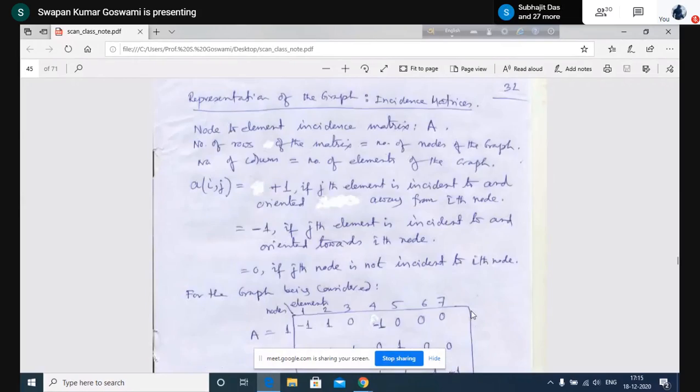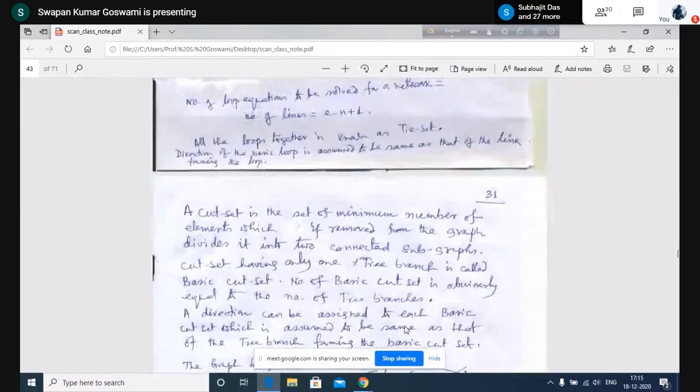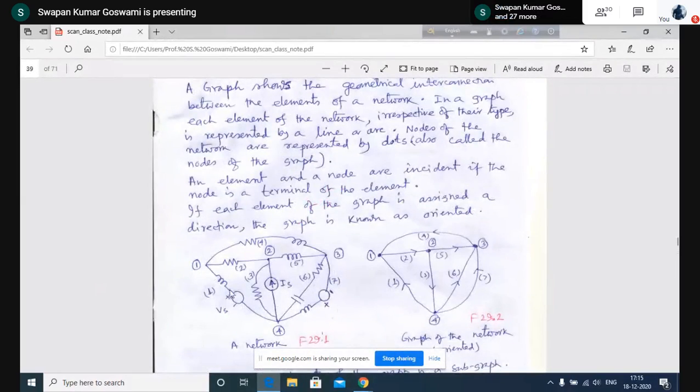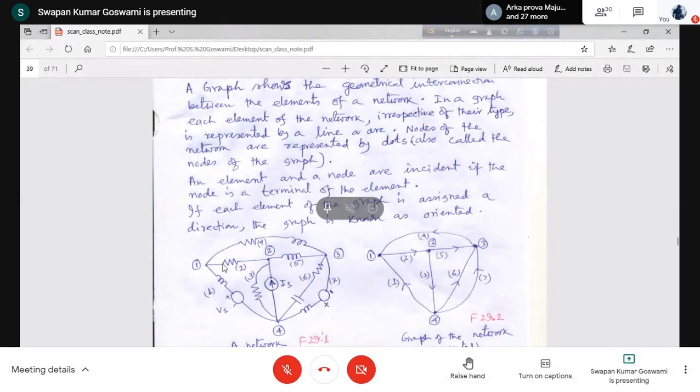How? You will see that in the final product, the admittance matrix that you obtain will have these values. At node 1, you will have y11 plus y22 plus y44. At node 2, we will have y22 plus y33 plus y55. At node 3, you will have the self-admittance y44 plus y22 plus y66 plus y77. And for mutual admittance, you will get minus y22 between the first row, second column.